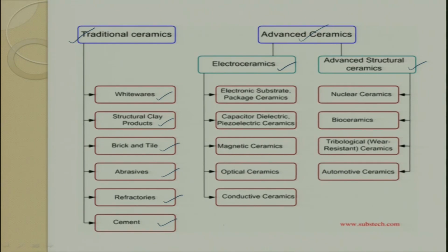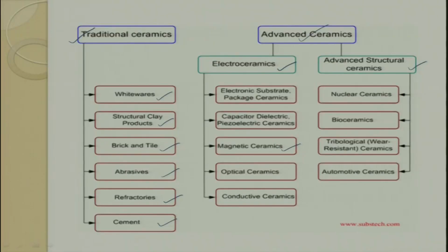This is a new area which has been there for the last 50-60 years, and today we are finding a lot of applications in these areas. For example, magnetic ceramics, which was not thought of, are now there, and we also have capacitor dielectric ceramics, which are for very small applications. We also have piezo crystal ceramics, where very small displacements are to be measured or to be given, we go for piezo crystal ceramics.